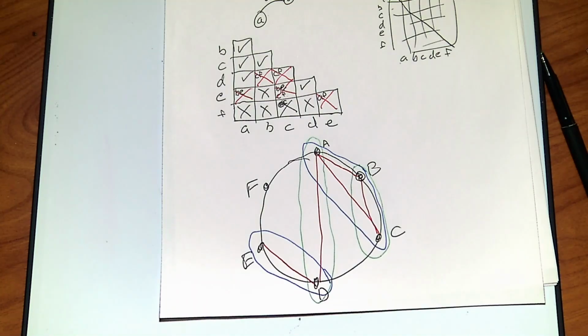To take care of the races, first I'm going to want to be able to do transitions. That's what we're doing with these primitive states. I first remove the input races, and then when I do my design of my states and change them from letters to codes, I'm going to pick a code system that doesn't give me a race. Good?